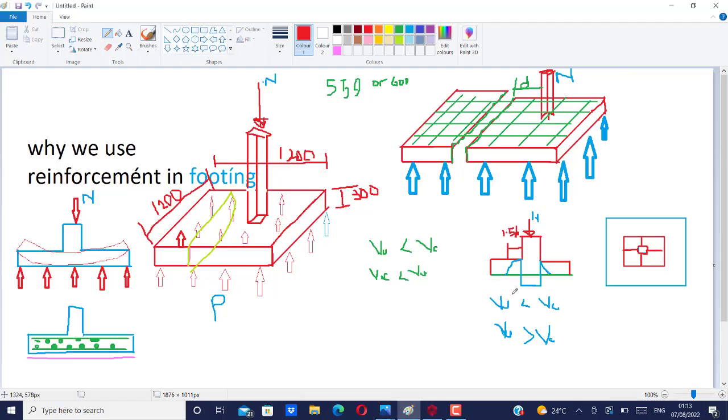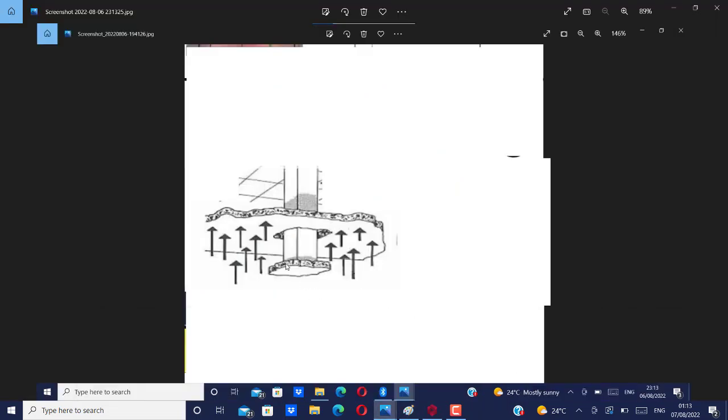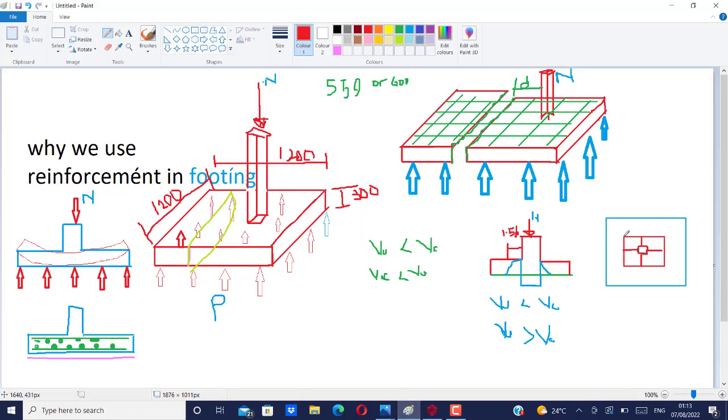So today, I want us to know that that's the reason we are doing this. And with this punching shear, you can see from this image how much of this concrete, when it punches down, went down with it. That distance is 1.5D. It has been discovered that there is possibility to push that whole area down from the face of this column. When it's punching down, it will punch through it. Also, that's what we want to explain here in our next class.